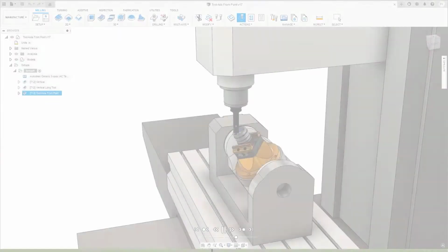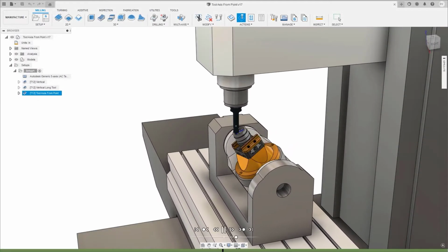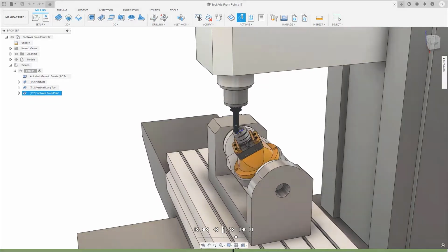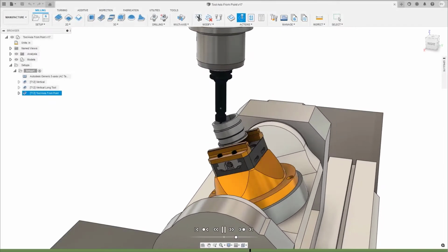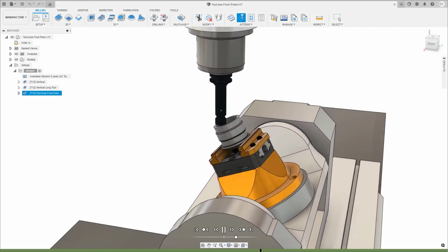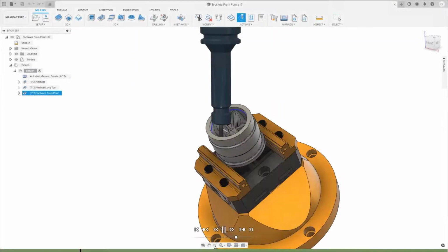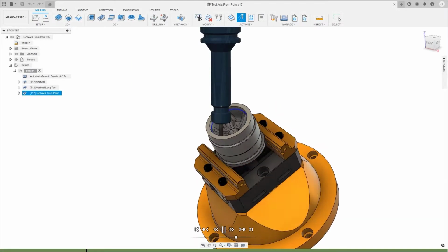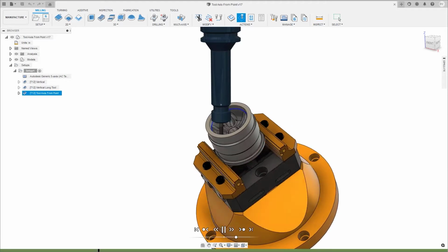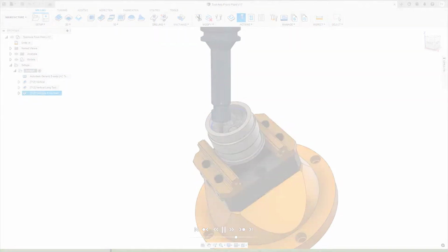To help with this, Fusion 360 has a range of tool axis definition options which can be predefined during the CAM programming process, simplifying your workflows and resulting in quicker success. Here we're going to look at how a tool axis can be defined orientated from a point. This often works well on concave formed part shapes which have an approximate rotational center such as this mold insert.